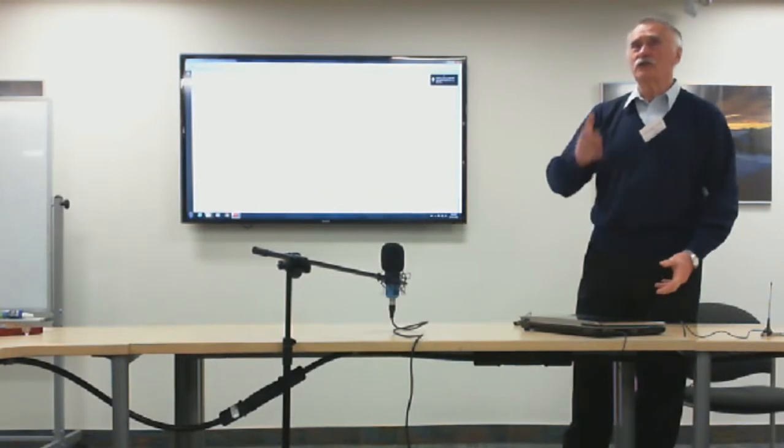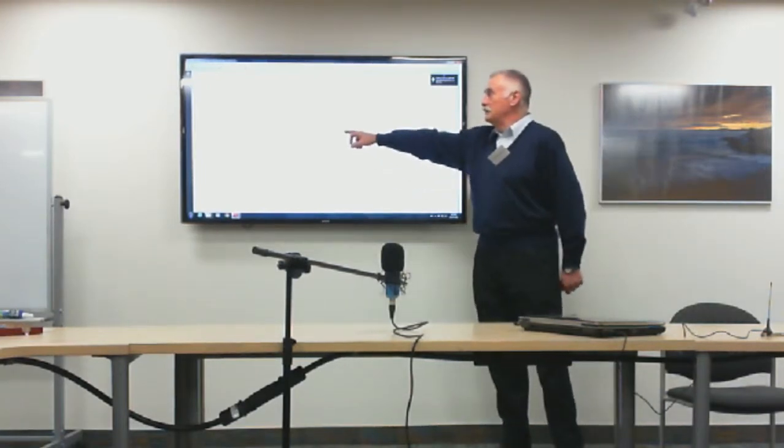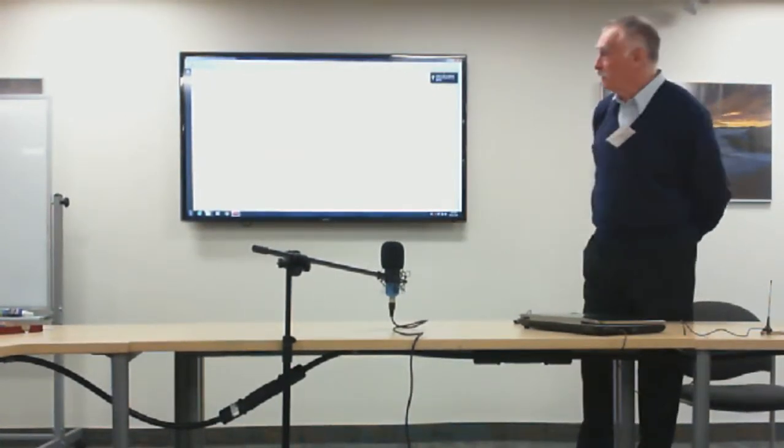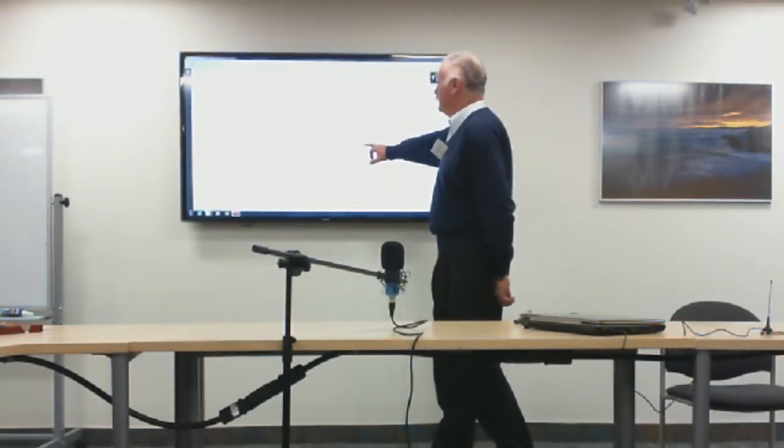Why is Industry Canada so generous? Because somebody there knows that electronic amplifiers do have an efficiency. The higher the frequency, we are lucky if we get 50% efficiency. The lower the frequency on HF, the efficiencies of ham radios may go up to 75%. So you apply 75% efficiency to 250 watts, you will get much less power on the RF output of your amplifier. We read further, and please bring this up here.